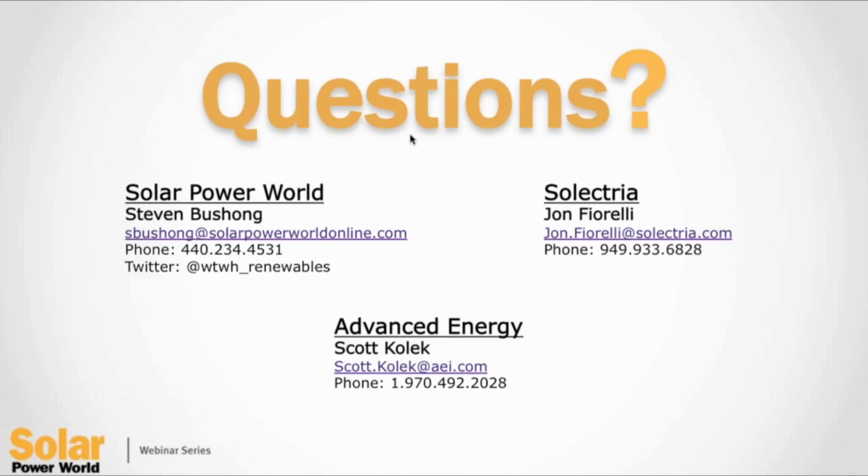And John, I think we have time for one last question. You mentioned that there are a few rules of thumb. Can you mention those? Oh, right. So rules of thumb. On one single MPPT channel, you don't want to use 2 different string sizes. That's kind of a best design practice rather than a rule of thumb.